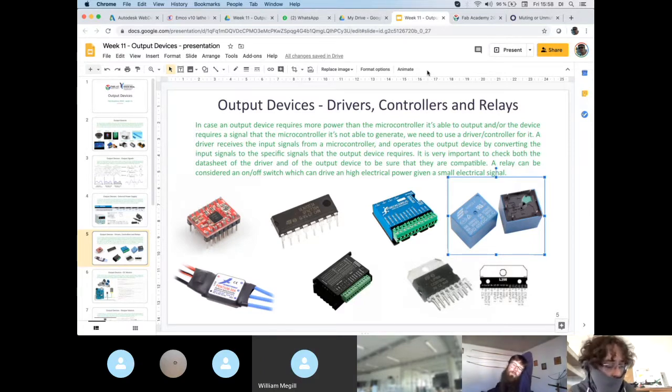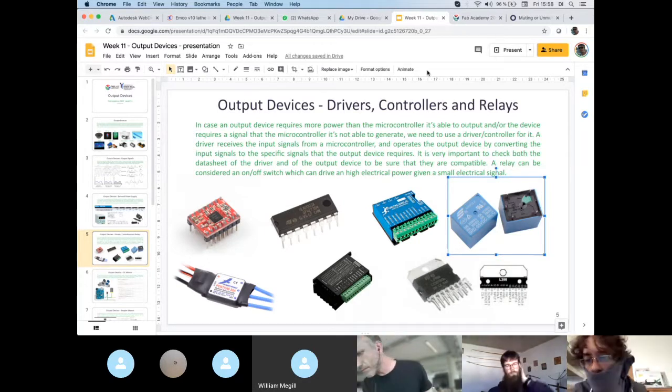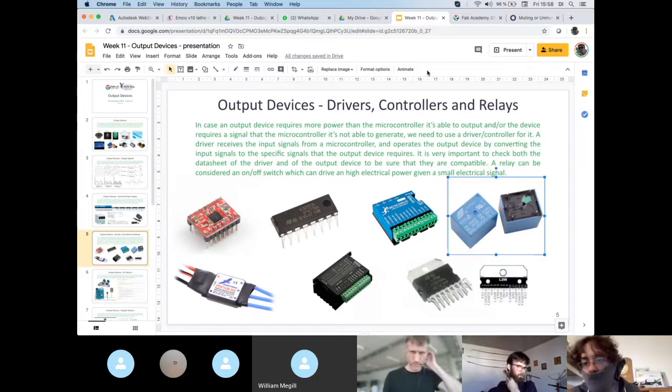So the solid-state relays, because they act as MOSFETs, sometimes have huge heat sinks, because they can do 50% of the power, for example, or 60% on, and they have to dissipate a lot of power. But the controlling mechanism remains the same. So if you send a specific signal to the relay, which is usually logic level high, the relay will trigger. Logic level low, the relay will not trigger.